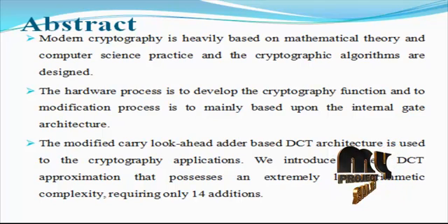In this paper, we introduce a novel 8-point DCT that requires only 14 additions for the DCT process. This proposed transform has low computational complexity and is compared to the state of the art DCT approximations in terms of both algorithm complexity and peak signal to noise ratio. The proposed DCT architecture is a candidate for reconfigurable video standards such as HEVC applications.